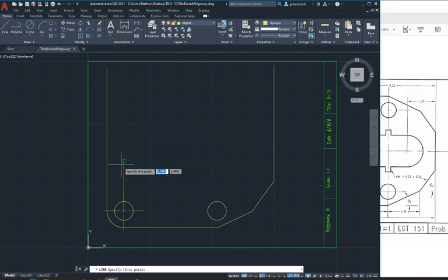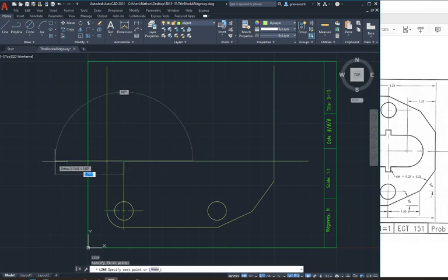The first thing I'm going to do is I'm just going to draw a long line out, escape, line tool again, long line out, and then escape, just so I have a center line. Next, I'm going to select anywhere on this line, and I'm going to come down at 0.78, enter, and then I can either come over or go back up.